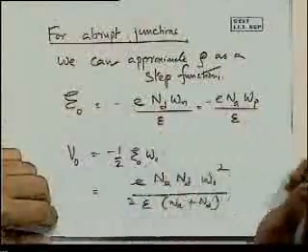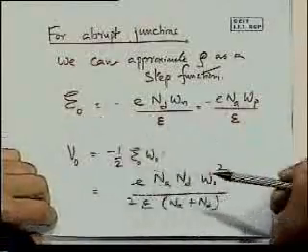I'm going to start off today with where we left off yesterday, namely with the p-n junction. Yesterday we looked at the p-n junction in equilibrium and no biasing conditions, and today we will take it up from there. Yesterday we had seen that we can make certain simple calculations and show that the built-in electric field is given by this expression.